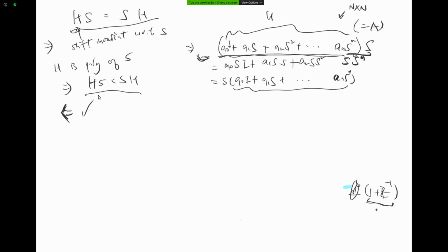It's not automatically satisfied. So on the surface, it looks like this filter has lots of flexibility, right? Because I have these a0, a1, and I can pick arbitrary values. It looks like I can have this polynomial extend indefinitely, but it's not right. Up to a certain point, it doesn't matter if you add more coefficients here. It just doesn't give you another filter, because of the so-called Cayley-Hamilton theorem in linear algebra.